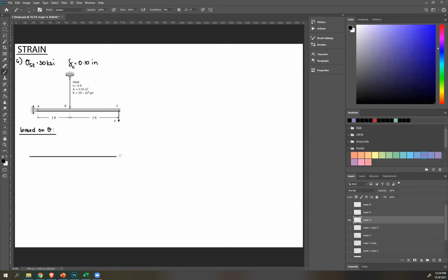Okay, we have P here. And then if I cut, I'm gonna isolate this portion, right? Wherever you cut, there's gonna be force there, and that's the force within your steel. So I'll just write that as PST. And then there's a hinge there. Remember for hinges, there's always a vertical, or not vertical, horizontal.